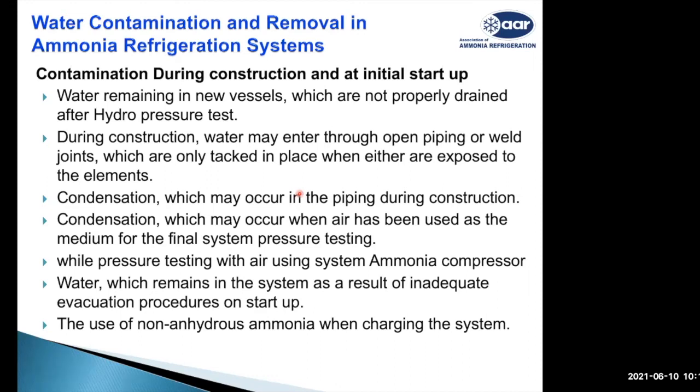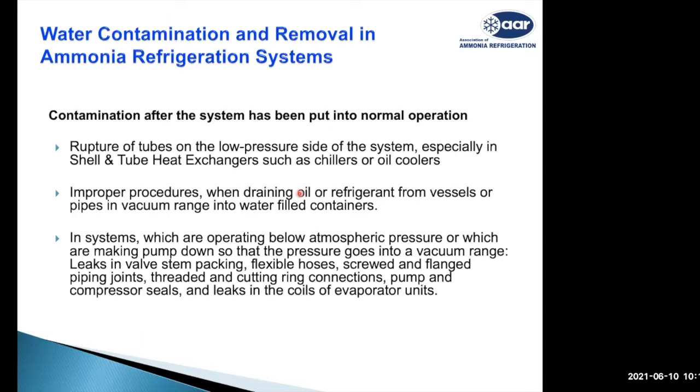The third thing is that there is a possibility that the ammonia which is supplied to you is not anhydrous ammonia. It may be hydrous ammonia, because many ammonia vendors do not provide a purity certificate for the ammonia which is being supplied. Sometimes, instead of bringing it in cylinders, a whole capsule is bought from an ammonia plant manufacturer, and then we do not know the water content in the system.